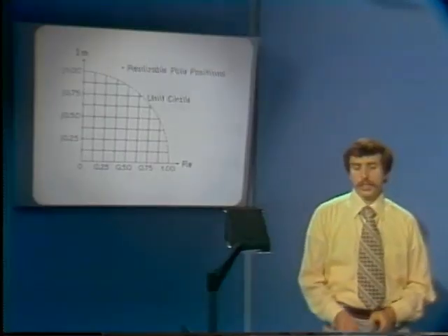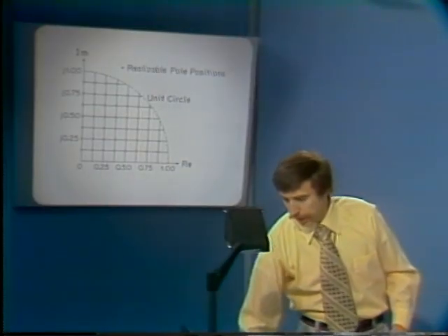So this last issue is simply an introduction to the fact that even given the notion that the cascade form structure is better than the direct form structure, there are additional issues involved in specifically how to implement a pole pair or a pole-zero combination in order to account for parameter quantization effects.